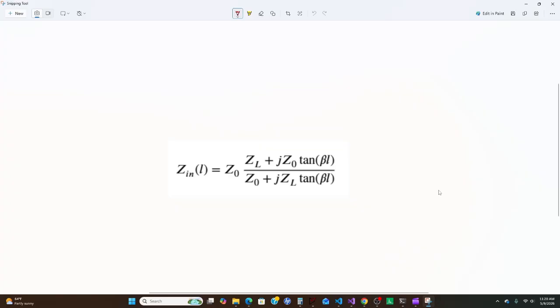If you're wondering how the distributed element filters work, basically it all boils down to one equation: how impedance shifts as you rotate through a transmission line. Because if you think about what is an open stub, but a perfect open rotated through a transmission line, same as a shorted stub. What is a shorted stub but a perfect short rotated through a transmission line? And then all you really need is your series parallel impedance equations to put everything together.